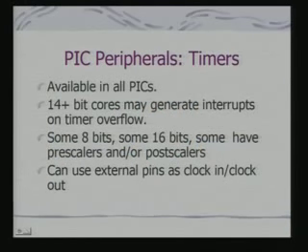Next we look at timers. Timers are very important peripherals for any microcontroller, because timers are used for synchronization with other devices, taking care of various timing requirements for control applications. And there are a number of timers, in fact typically 3 timers on mid-range PIC microcontrollers. And what do we mean by the 14 plus bit codes? When your instruction length is 14 bits, these codes enable the timers to generate interrupts on overflow.